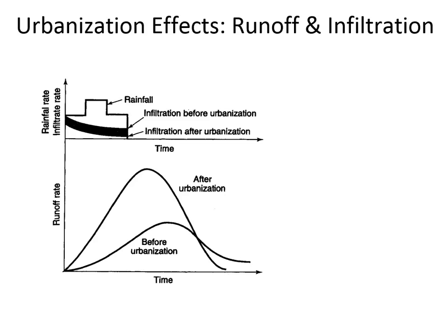And so look at the before and after urbanization. What it shows is that after urbanization, the infiltration rate is lower. And that coincides exactly with what we're seeing here. If the soil is absorbing less water, in other words, if the infiltration rate is lower, then we're going to see a higher hydrograph peak. It will peak sooner and it'll peak higher than it did before.